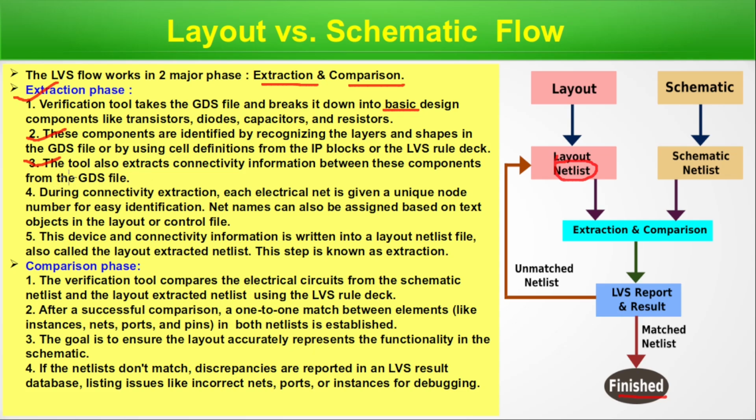The GDS file is full of geometrical structures. All the devices and everything is represented. That is the layout, basically, represented with geometrical structures. Layers after layers after layers. So extraction of information is done from those layers.